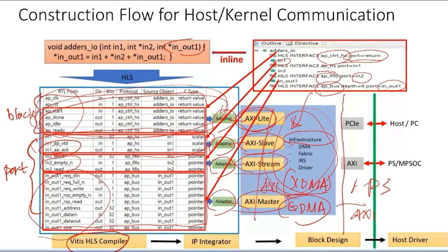So after the block design is done, you can generate the bitstream, and with the bitstream you can start running this FPGA. On the host side, there's a host driver to communicate with the infrastructure components and also with the kernel functions. Okay, right now you know the whole process.